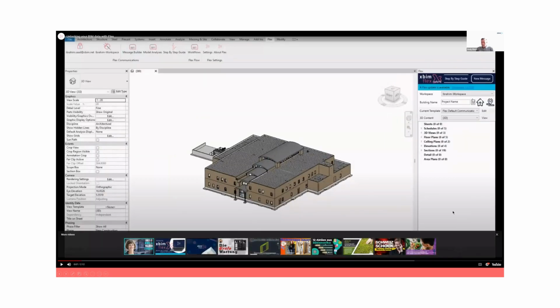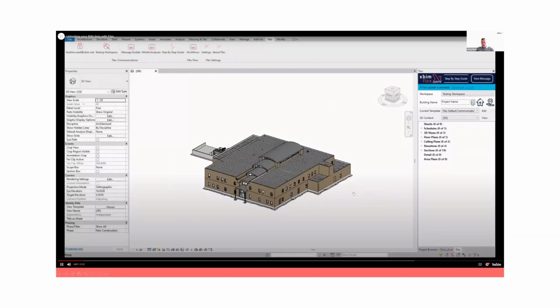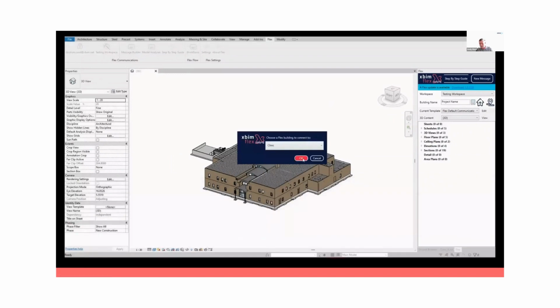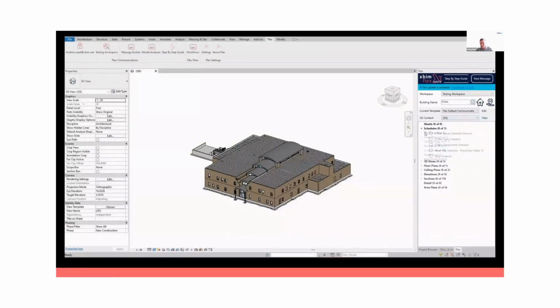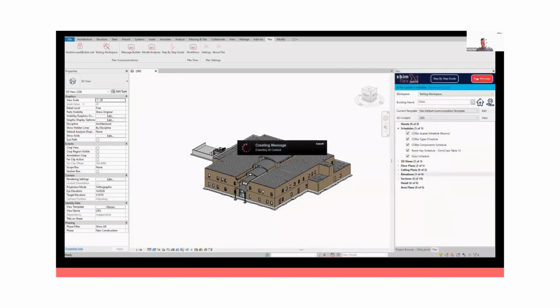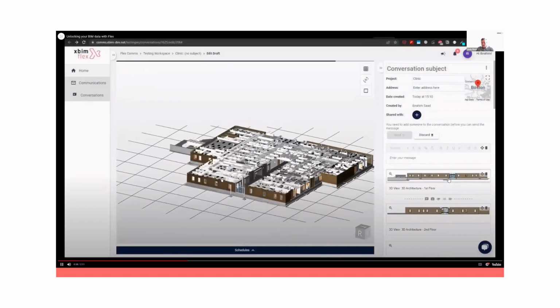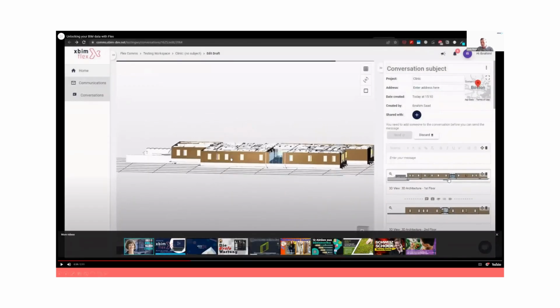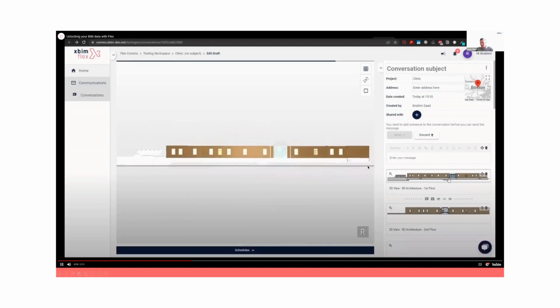What I'm showing you here is our Revit add-in. It's an add-in into Autodesk Revit that lets you take BIM data out and put it into an open BIM form and into an AIM in a quite simple, repeatable set of steps. You can take a complex, federated building model and extract floor plans, drawings, schedules, asset registers, all the semantic data, all the 3D data, and a lot of the documentation from that model. At this point, it's open BIM. It's turned from a proprietary data source into an open data source, and it's turned it into an AIM as well.